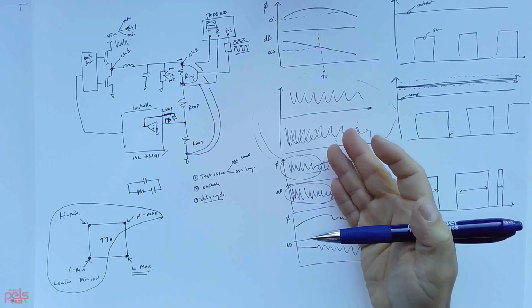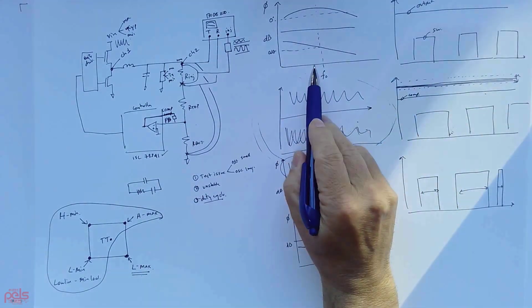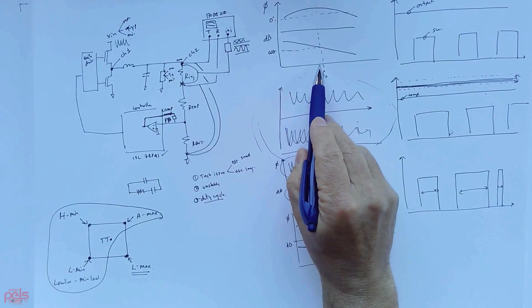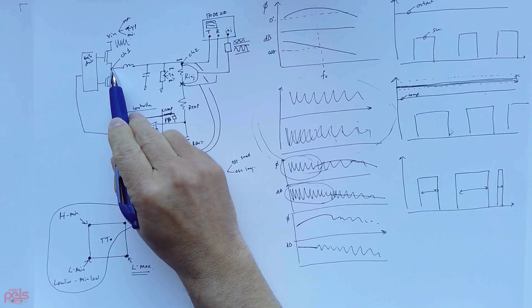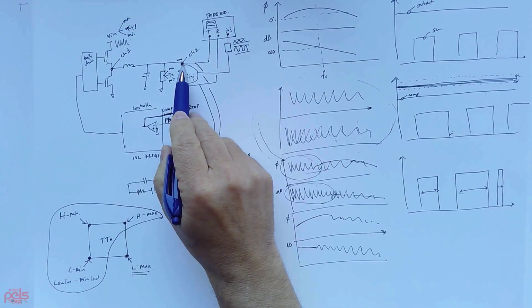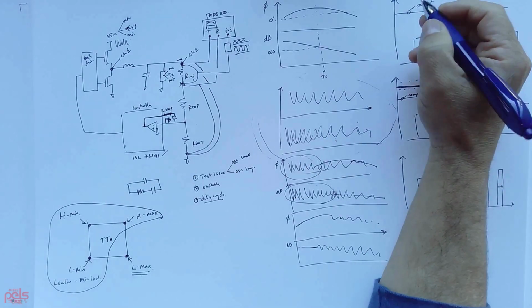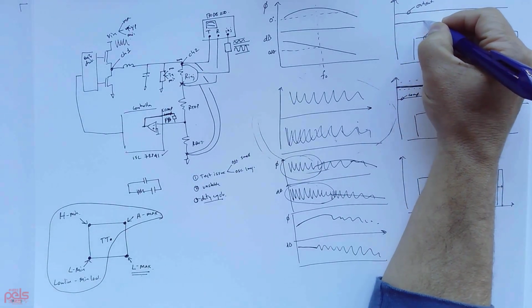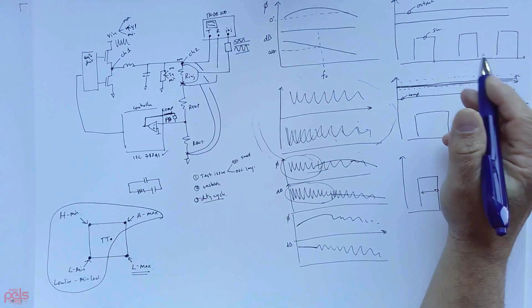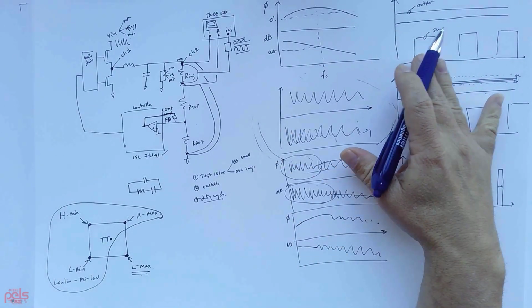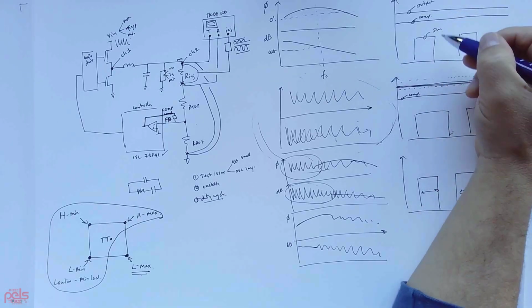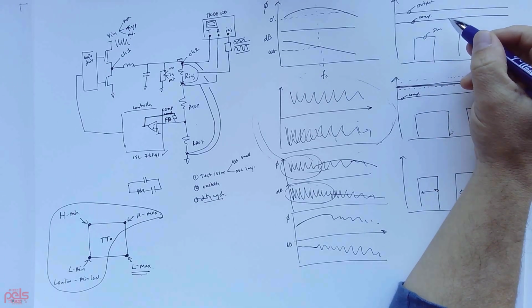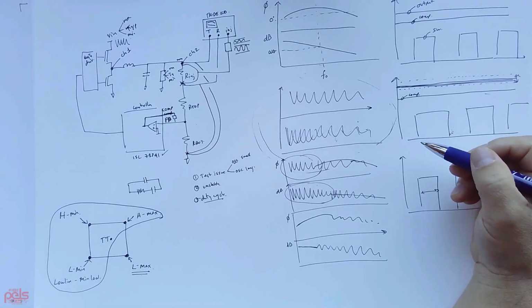What I recommend that you do is that as you take your frequency response plot, you have a scope right next to it that shows you the switch node, the output voltage, and the COMP pin. So this is the big takeaway from this video. As you get your frequency response, plot the switching node along with the COMP, know what the limits of the COMP pin are, and that'll tell you if you're running out of duty cycle.